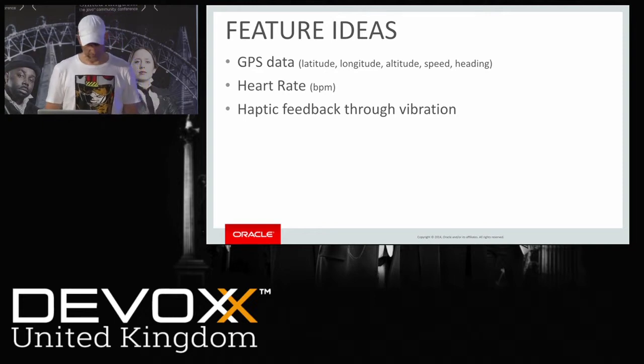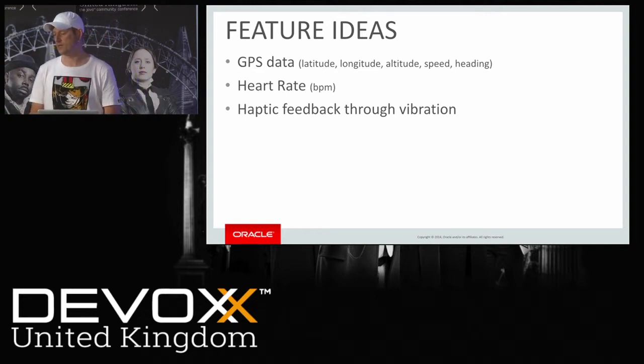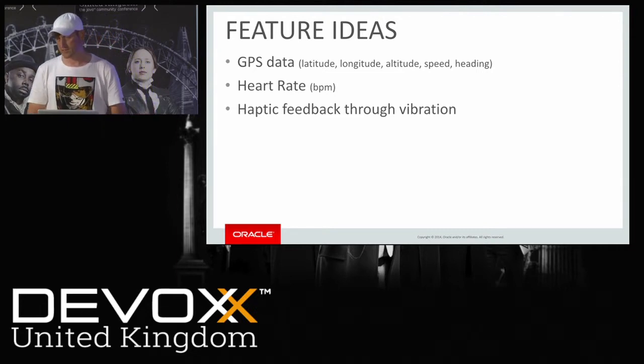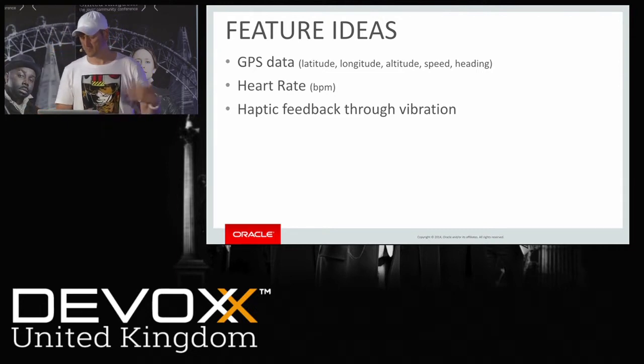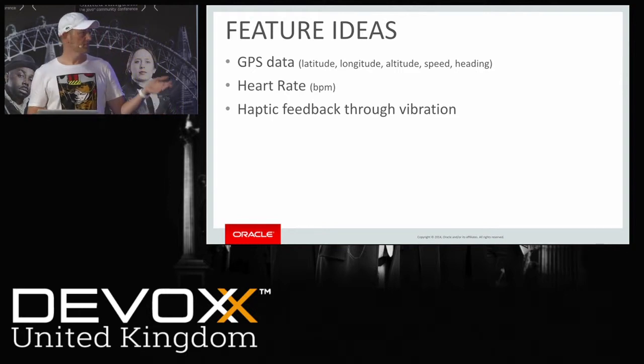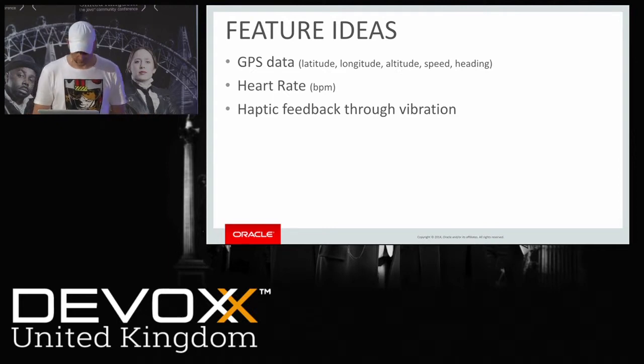Then usually if you have some kind of a lithium polymer battery, you have to switch it off, not when it goes down to 0, but maybe at 10-15% to really make sure that the battery will be alive the next time you charge it. And for that kind of reason, I needed something like vibrational feedback in this device.